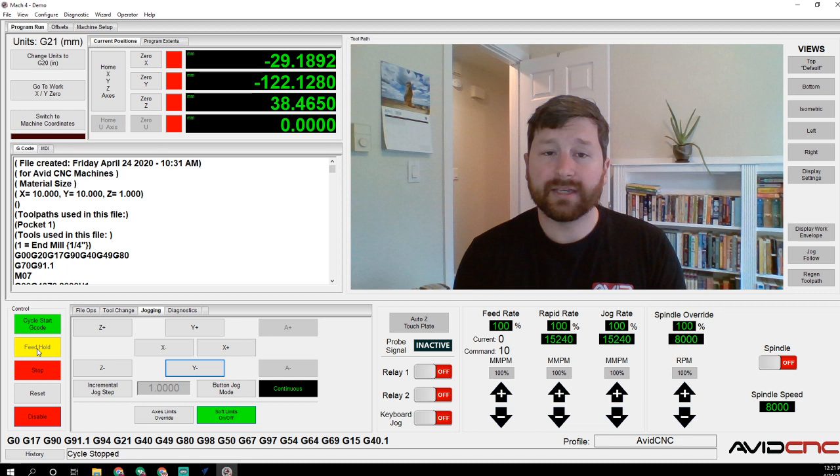If I have a longer program, I will go back into my CAM package, and I will use the same 0, 0 position, and I will just reprogram the rest of the parts that didn't get cut out, right? And when you do it that way, you're starting a fresh new program, and you're only cutting the areas where you haven't cut yet. You're not going to do any air cuts, and you know that you're going to start exactly where you expect for it to start.